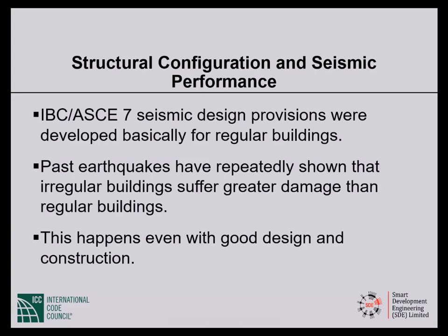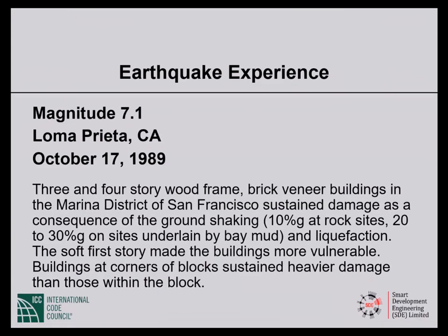And this greater damage to irregular buildings happens even with good design and construction. Okay? So, good design and construction. I just said that you can design to have irregularity in your building, but it has to be properly done. Okay, just regular good design, it will not suffice.